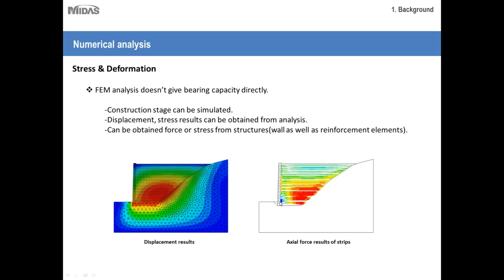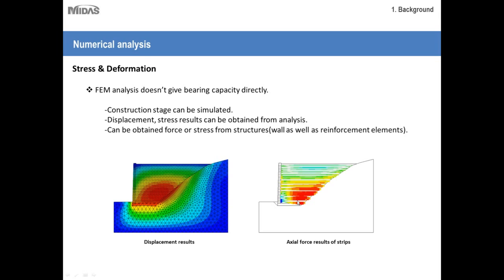This is because we started erecting the structure from bottom to the top. As and when we started putting in the backfill, the lower part of the structure would start deforming, and that is why we have the retention system or reinforcements. So they will hold it in its place. So that leads to excess or higher axial force in the bottom part.